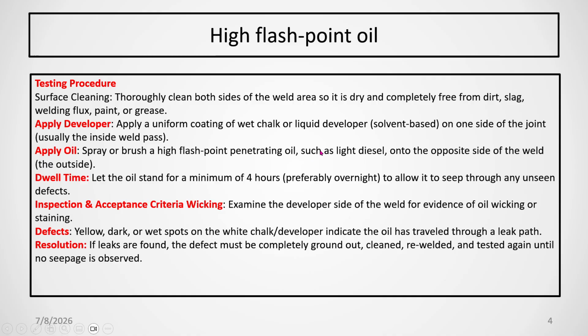Developer means a liquid developer, solvent base, so that it will penetrate on one side of the joint. If it is plate or welding, on one side of the joint you have to apply the liquid developer or white chalk. Then on the other side, spray or brush a high flash point penetrating oil, such as light diesel, on the opposite side of the weld.